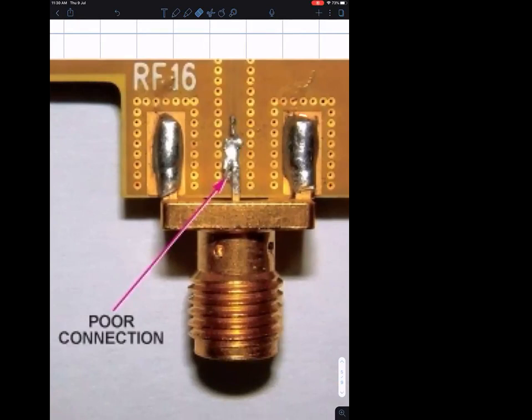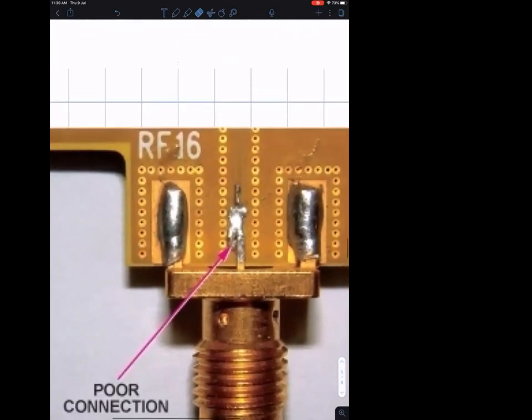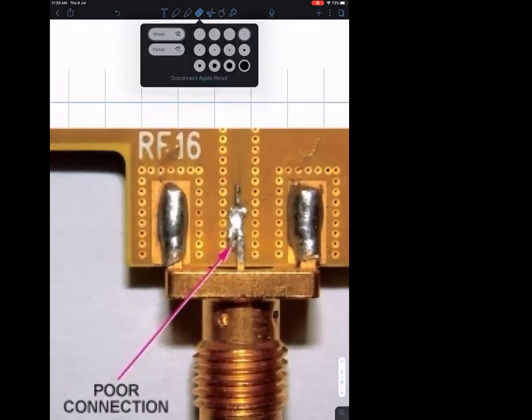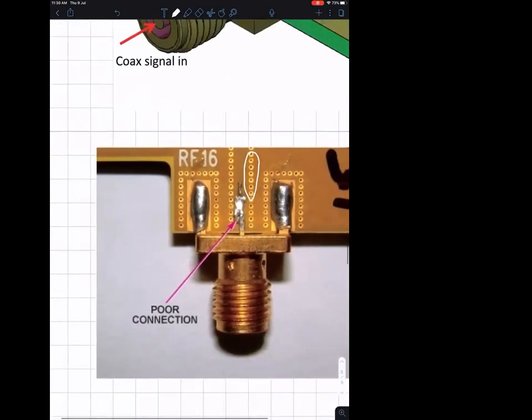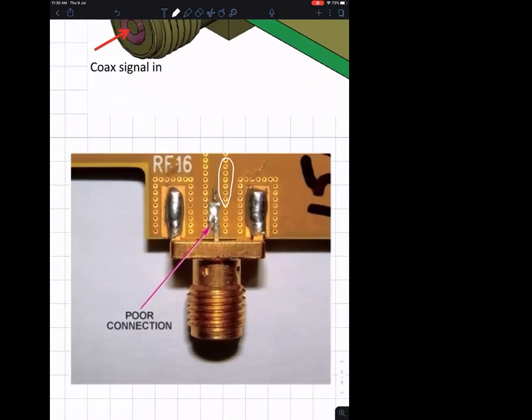So the body must be strongly connected like this. But in this case, most of the time when we did our fabrication in the lab, we don't have the ground plane on the top, right? We only had the bottom ground plane. But they have a ground plane on top also, which is much better. And then they use these vias to connect the top ground plane to the bottom ground plane. Because as I told you earlier, the ground return must have very low impedance.